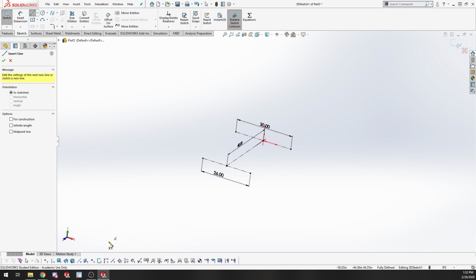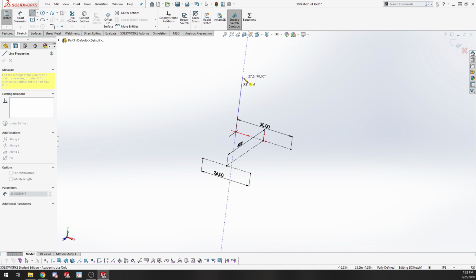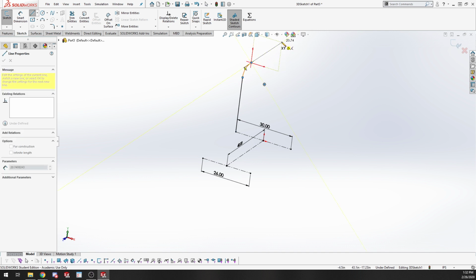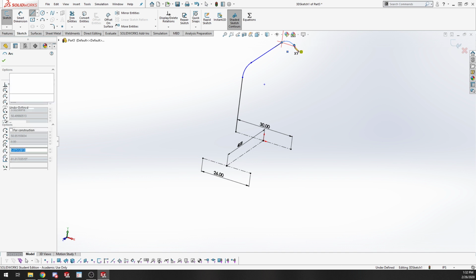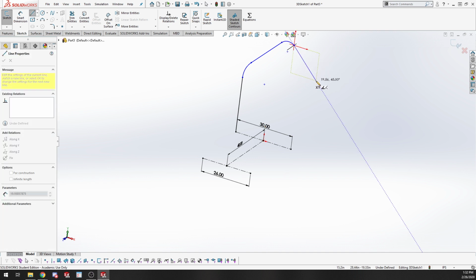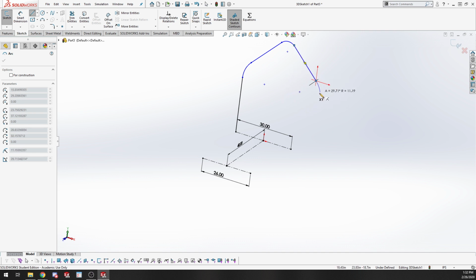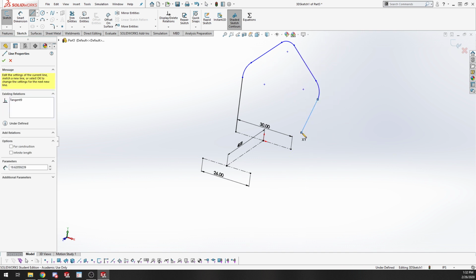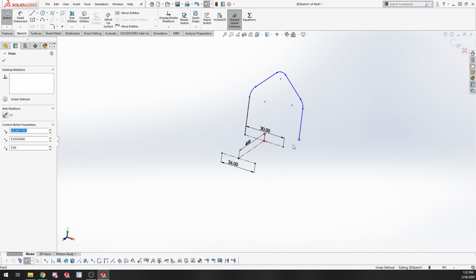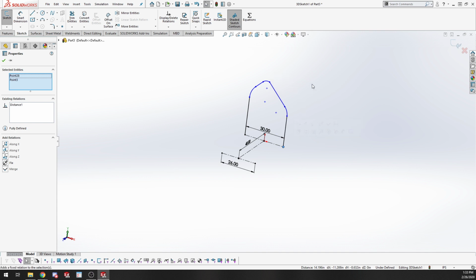So just making sure we're on XY plane, so yeah, going up. And if you remember with sketches, we can just hover over the endpoint to draw in a radius. Go up. It's a super rough sketch here. Going straight, line. Tangent. Oh, it's really rough. And then down. Alright, so this one, we need it to be along Y. Merge those two points together. Make these two equal.